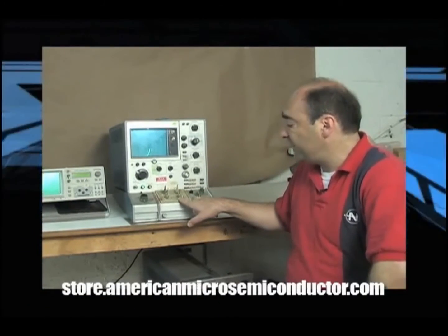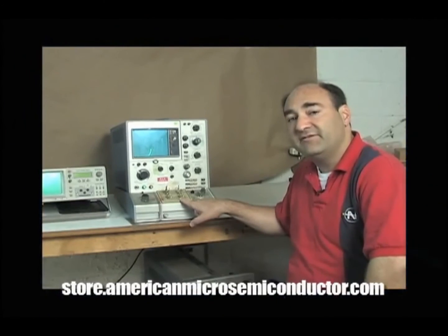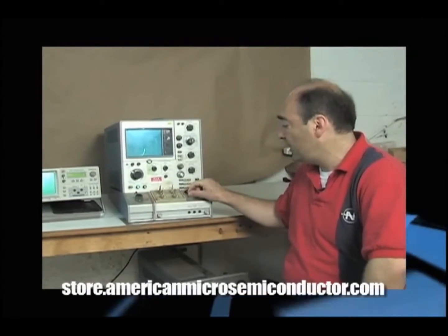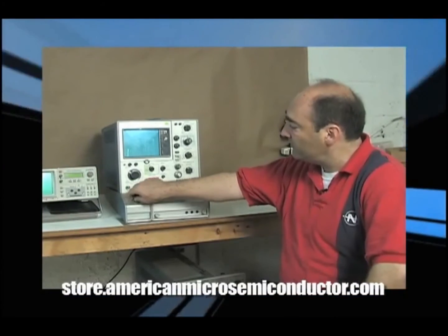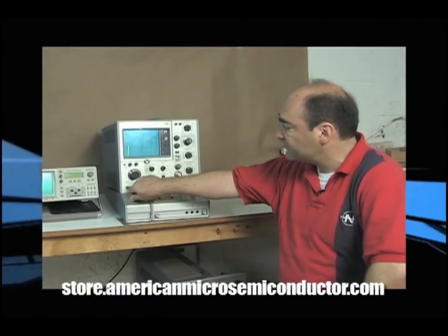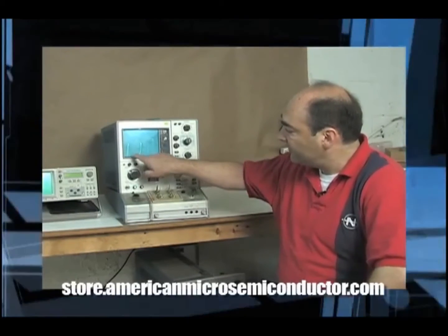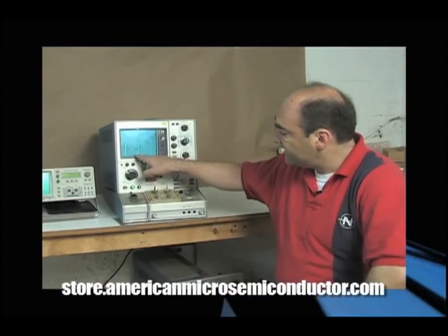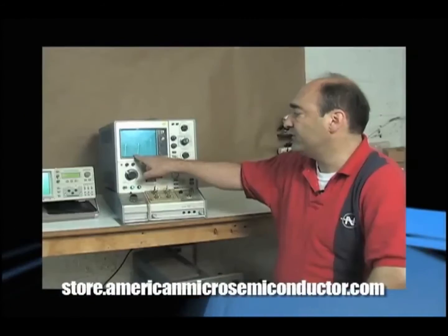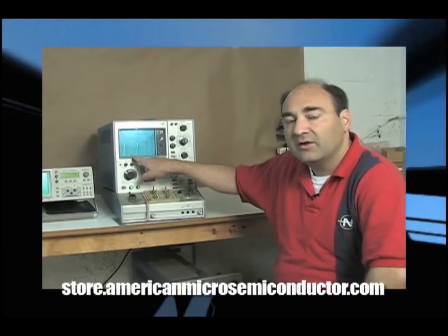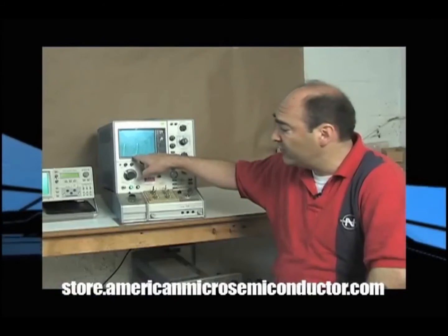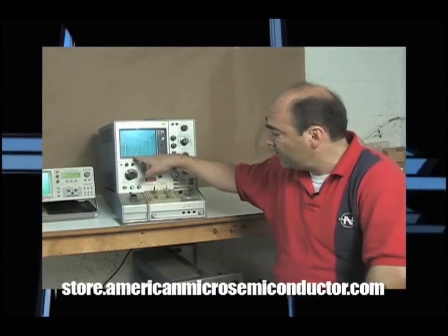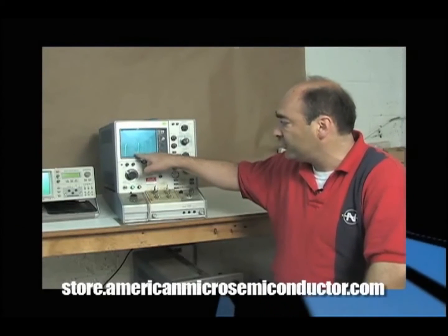Now, on the right-hand side, we are looking at the 1N3713 tunnel diode. I'll flip the switch. And now when we start forward with the characteristics, you'll start noticing this region in this area is referred to as your negative resistance area. It is in here that we do not see a curve, but that tunneling does occur. In this range is where you're going to be getting your quantum principles realized.